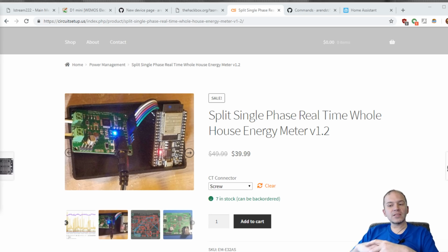Yeah, Will, that's that whole home monitor. It's got a little DIY to it. I do have a custom sketch for it, and it does work pretty well. I do need to go fix one issue with a timer count on the Wi-Fi that'll automatically reboot the board. It's one of those ESP issues. You can use an ESP32 or an ESP8266. I think he's showing it using an ESP32. I'm using an ESP8266.